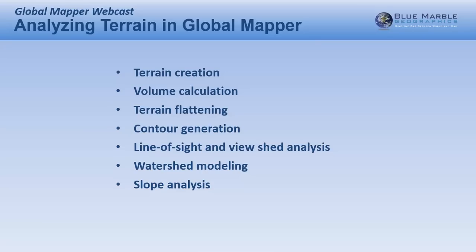Slope analysis: there is a visualization that can be applied to any terrain layer to determine not the elevation at a given point, but the angle or indeed the bearing of a slope. And we can take that information and do a little more analysis. I'm going to introduce a very interesting visualization based on our quiver plot generation functionality, where you can visualize the slope characteristics at defined locations, and maybe again to determine the optimal location for an engineering project or a construction project. But being able to determine that visually on the map, very, very simple but very powerful function.